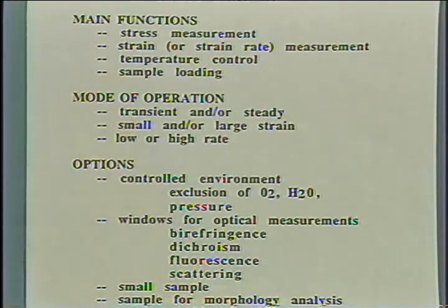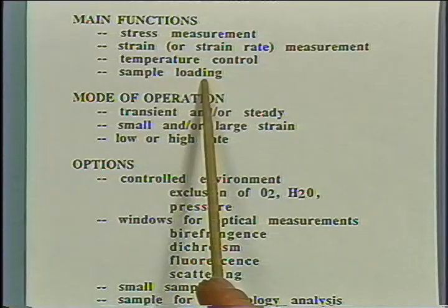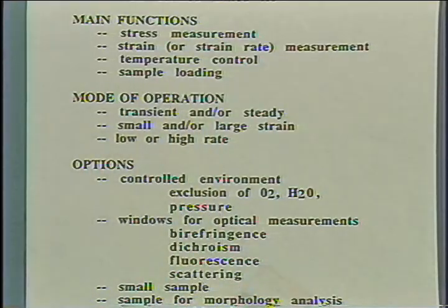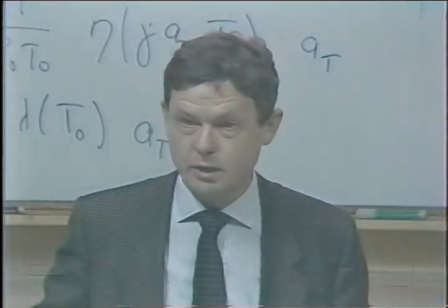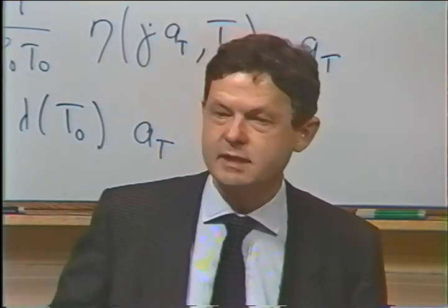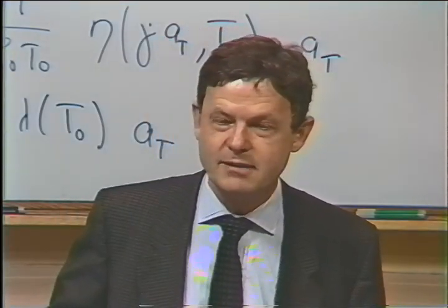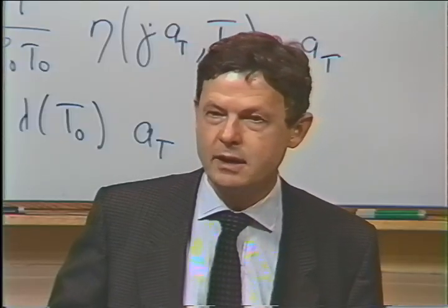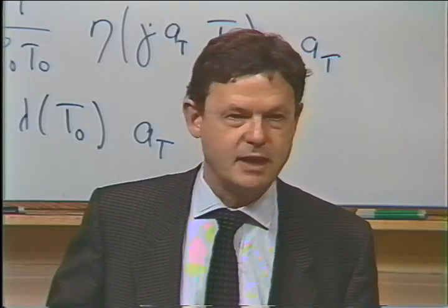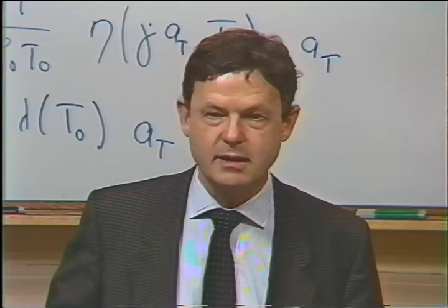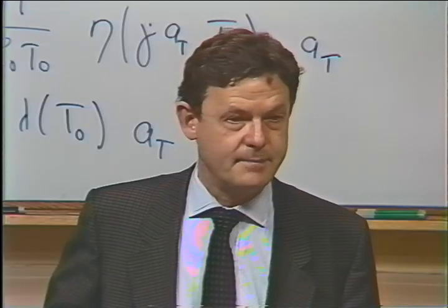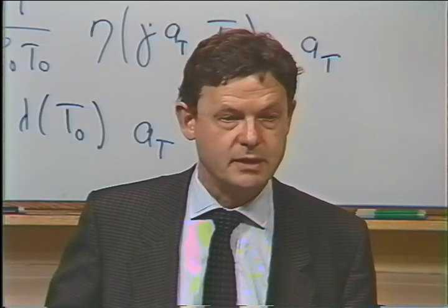So this is connected really with the problem of molding. We not only want to load it and then unload it in some fashion, we would like to unload it so that the sample is intact, and we can look at the morphology which we introduced into the sample by some fancy type of flow. We can use flow, for instance, to push the material away from equilibrium, produce some interesting morphologies, maybe some chain extension, and quench the sample with that interesting morphology.